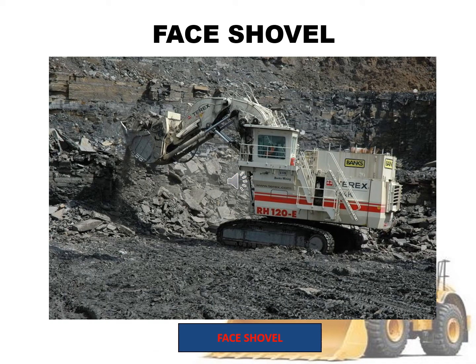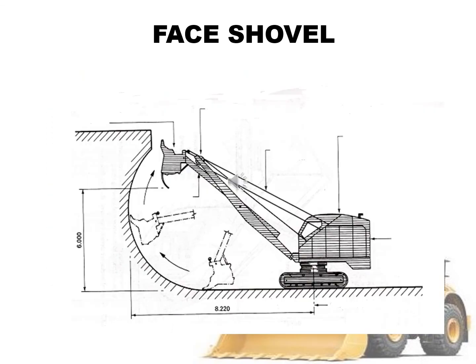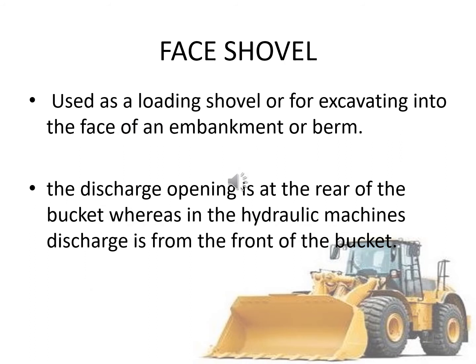This is face shovel. Please complete the label for face shovel. Face shovel is used as a loading shovel or for excavating into the face of an embankment or berm. The discharge opening is at the rear of the bucket, whereas in the hydraulic machines, discharge is from the front of the bucket.